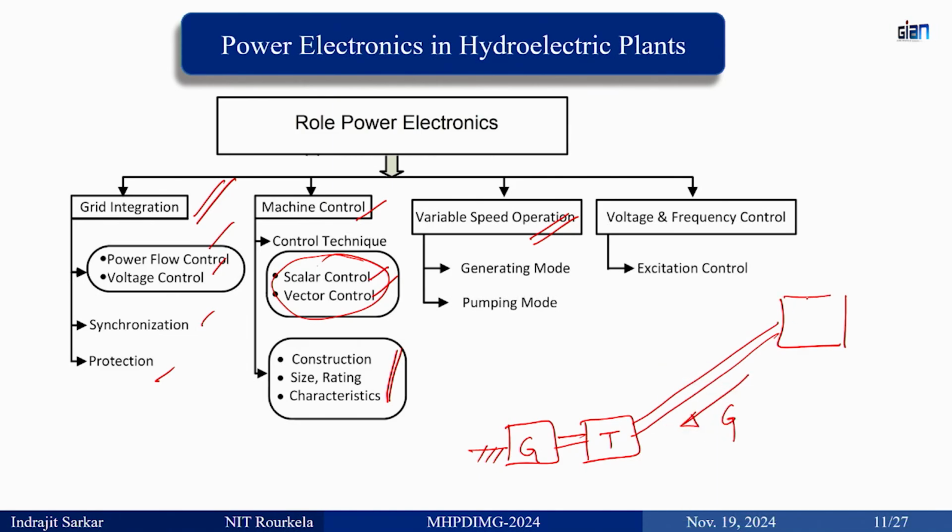Using this water, potential energy is converted into electrical energy. When excess power is there in the grid and you have to maintain the grid frequency, what happens when grid power increases? It is not like a DC bus; the frequency of the grid will increase. Why? Because the synchronous generator that is running is getting excess power, its rotational speed will increase, and eventually the frequency will increase.